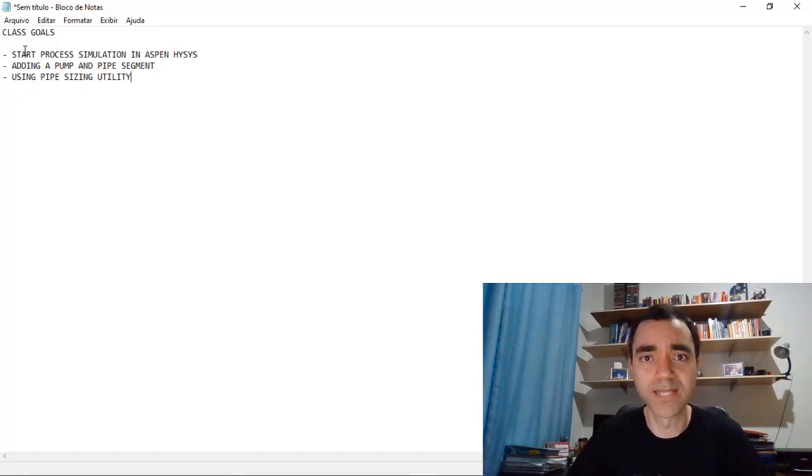The 3 goals that I have with this class is to show you how to start a process simulation, so I will explain the procedure to start a process simulation in Aspen Hysys. Moreover, we will see how to add a pump to your process simulation and a pipe segment also, and we will see how to set that up. And finally, I will show you how to use the pipe sizing utility in Aspen Hysys.